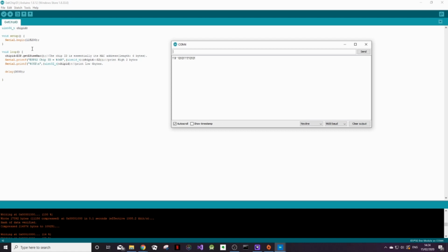I won't go into serial baud rates now. We will probably cover it in another video, but all you need to do to get this example to work properly is to set the baud rate to this number, 115200. So if you come over here and set your baud rate to 115200, there you go. You can see that it's now communicating information in characters that we can read. It is simply outputting the ID of the chip. And there you go. You have successfully downloaded your first sketch to your ESP32.